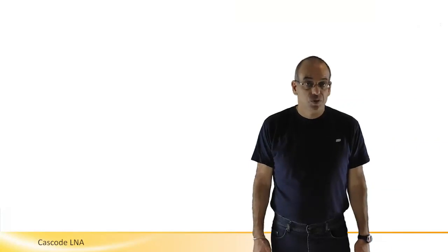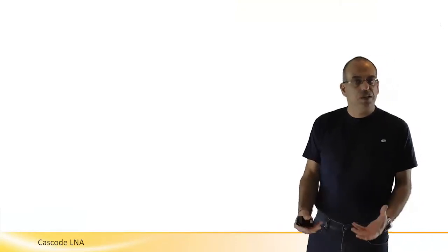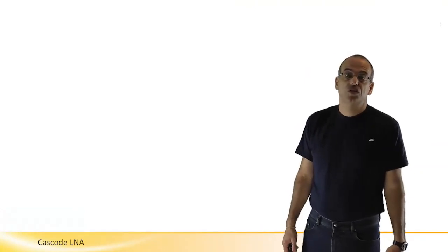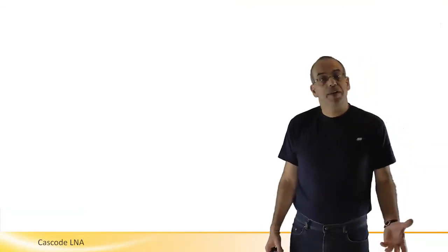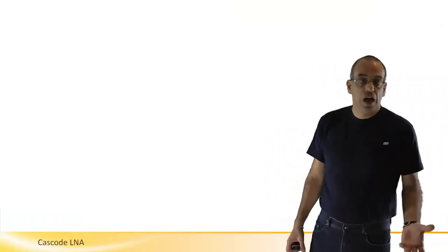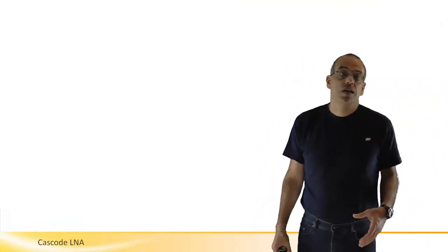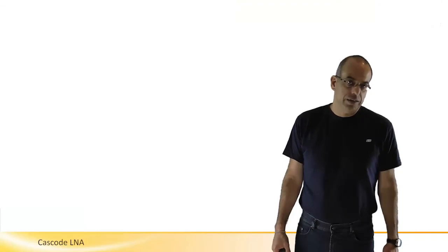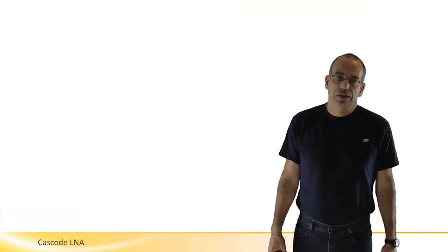Okay, in this tutorial we have introduced the Cascode transistor, and we have finalized it with the Cascode LNA. We have found that the Cascode transistor has stabilized the circuit, increased the bandwidth. We explained how it increases the output resistance and the input-output isolation. The Cascode topology is very common in LNA design, and it is heavily employed in RFIC circuitry.